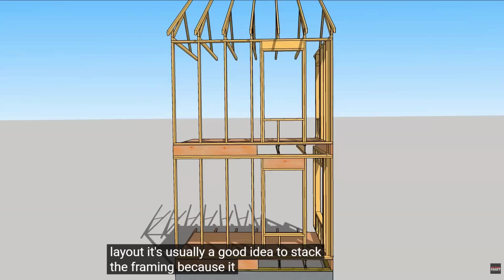If you're totally into energy efficiency, there might be this very, very marginal benefit, but all the hassle you have to go around to line up your floor joists on your levels and line up your trusses and make sure all the studs line up and where you put the openings, it's not worth it to me.